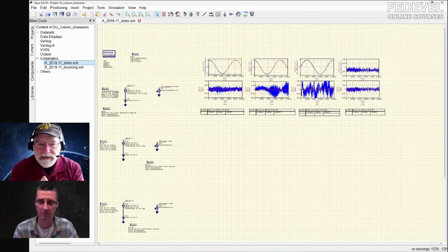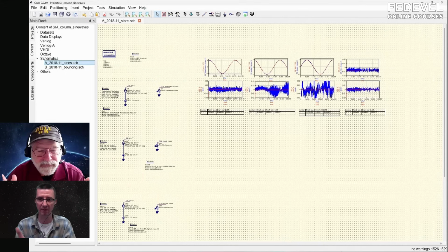There are high-end tools like Keysight ADS or Siemens Hyperlinks or Cadence has SI Wave. These are high-level tools, much more sophisticated, that will take the layout information, turn it into S parameter behavioral models, and then incorporate the circuit simulation. So you can now predict what the waveform looks like. You send a driver in on one end, and here's what the signals look like at all the other terminals as well. We sometimes call those system level simulators. They include the environment and everything.